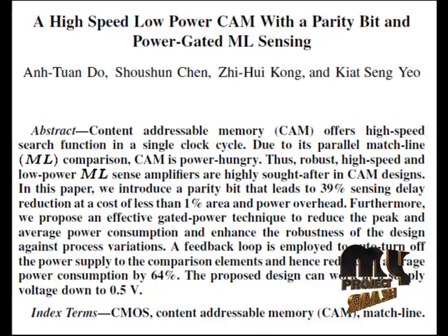Next, the search line drivers broadcast the search word onto the differential search lines, and each CAM core cell compares its stored bit against the bit on its corresponding search lines. Match lines on which all bits match remain in the pre-charged high state. Match lines that have at least one bit that misses discharge to ground. The MLSA then detects whether its match line has a match or miss condition. Finally, the encoder maps the match line of the matching location to its encoded address.